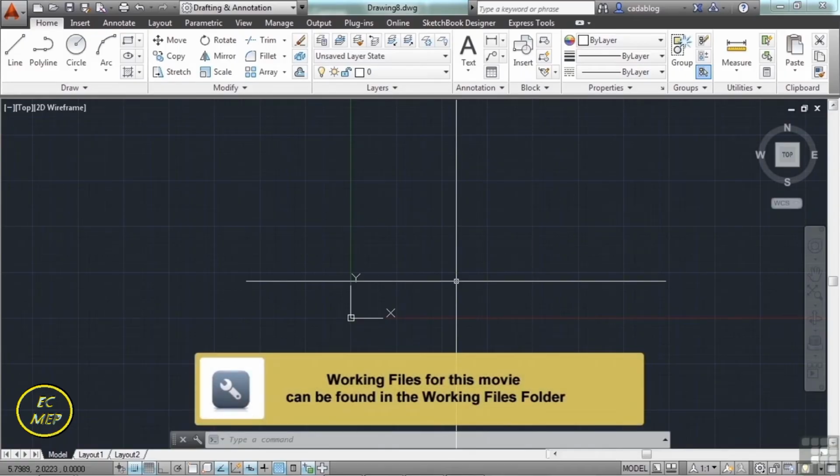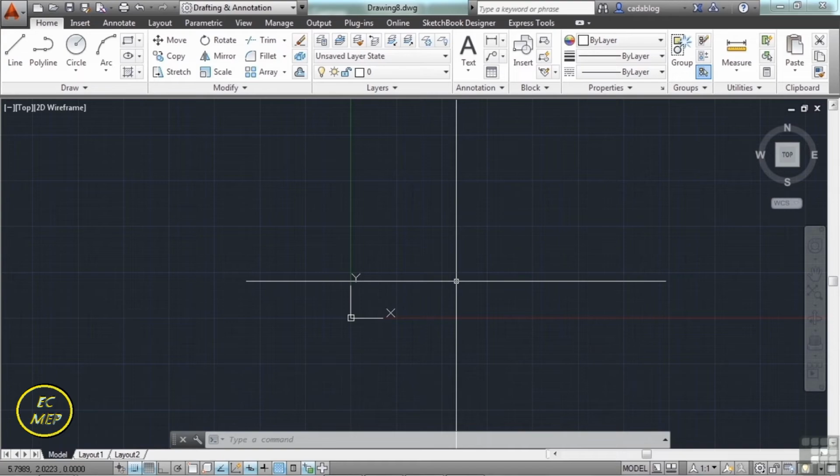If you have more than one object in your drawing, and trust me, you're going to, you will find that you need to navigate within your drawing. One way to get back and forth in your drawing is to use the pan command. Panning is not that difficult, not anymore. For many releases, we have had real-time panning. That means that you can see where you're panning and the screen moves along with it. There are many ways to get to the pan command.